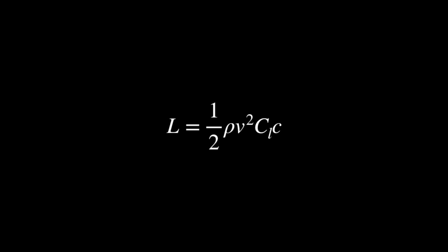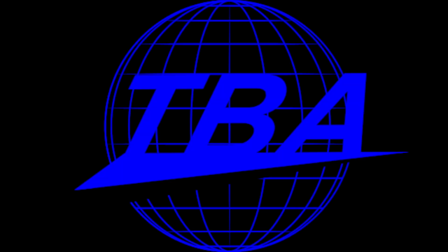Of all the parameters I mentioned, the coefficient of lift is probably the most important parameter that is studied widely throughout aerospace engineering. The coefficient of lift is a non-dimensional value that is used to describe how well an object can produce lift. It can be argued that the coefficient of lift is actually a function of the object geometry as well as the object's angle of attack.